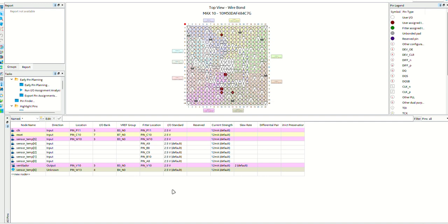Actually, we're using a buffer because the relay model works with negative logic. So it needed a 0 in order for the relay model to close the circuit and start energizing the fan. But whatever the reason, when we sent a 1 to the relay model, it was actually working, so I don't understand quite well, but with the buffer it stopped getting that issue and started working correctly.